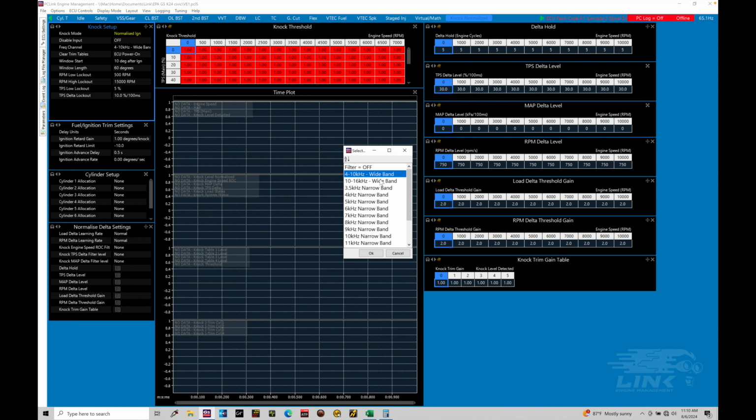This is used if you're looking at the first order frequency or the second order frequency for a Bosch flat response style knock sensor. So this is saying that we can look over a broad band of frequencies where those flat response sensors are much more reliable compared to a resonant sensor. Resonant style sensors, an OEM sensor, you'll find a lot of the older 90s, early 2000s era Japanese and OEM, even domestic engines. You'll find that those are a single wire. That's how you distinguish between typically flat response or resonant, although resonant can have 2 wire, but typically they're 1 wire.